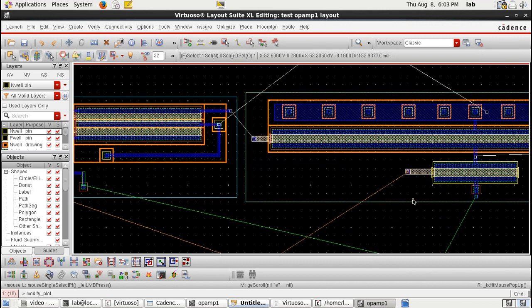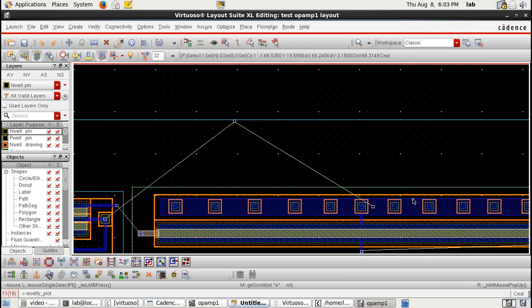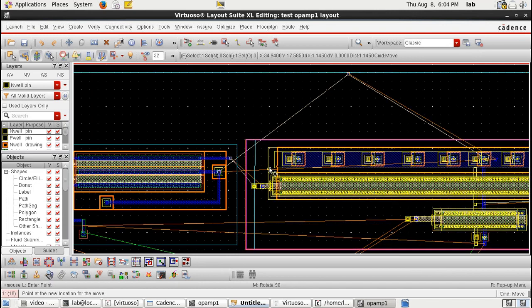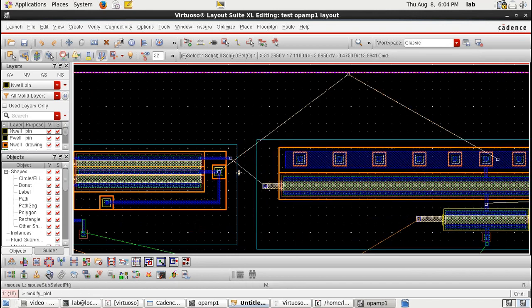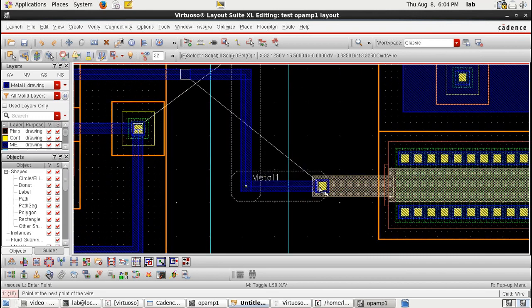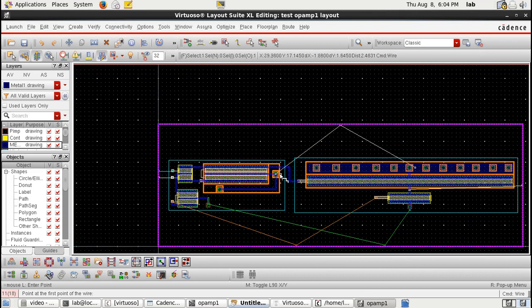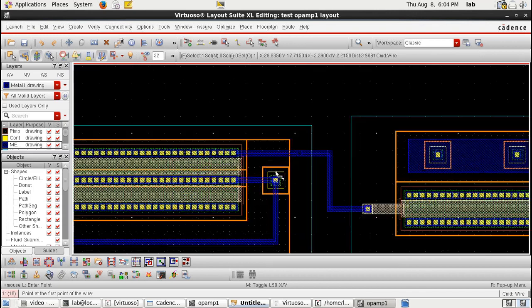So we can see that the VDD terminals are here, and there is a connection here. Now this connection is the tricky part in this layout actually. So we have previously only used one metal when we wanted to make a connection. We've only used metal 1, but in this design metal 1 alone will not be sufficient because there are some paths that we have to cross over, and taking metal 1 over metal 1 will fail for us catastrophically.